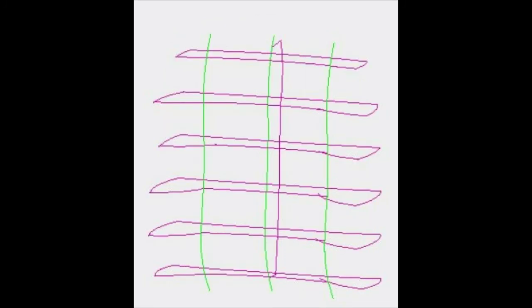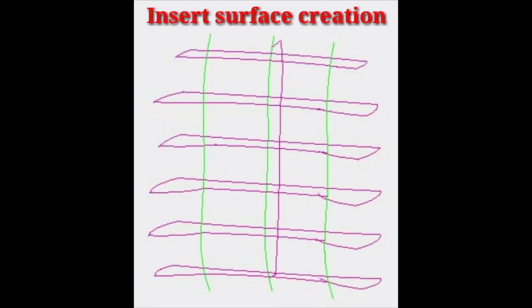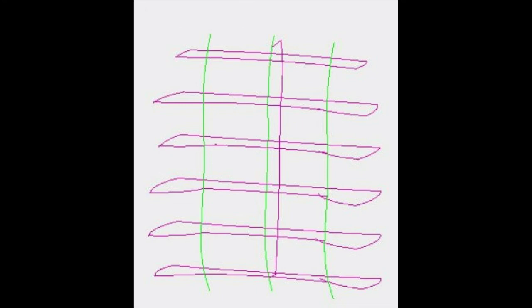The insert surface creation uses the same technique as the side and bolster surfaces except for the driving curve. Since the center line of the pad profile is the most critical part of the insert surface, the driving curve is created using the intersection point of the insert curve and a plane which is parallel to the y-axis through the center line of the pad.